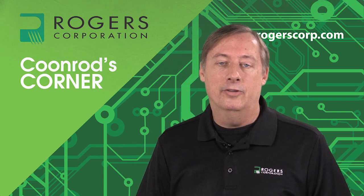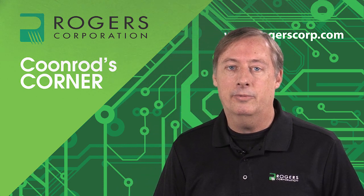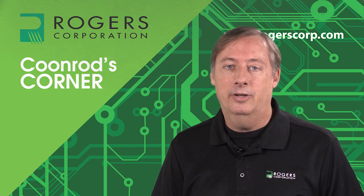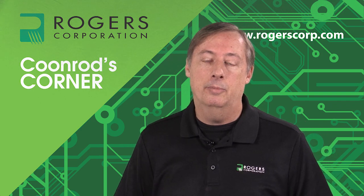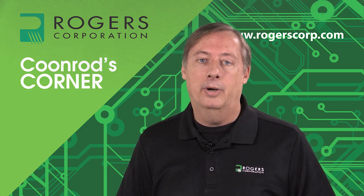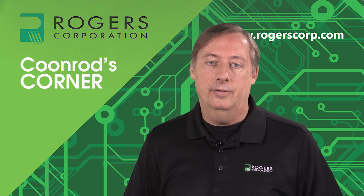We have found over time, as well as our customers, that the design decay values that we generate with a microstrip transmission line can be different than the decay values from other test vehicles. And that does make sense, actually, when you put a little bit of thought into it. So I'm going to explain some of the concerns here and why you can get different decay values on the same material when used in different test vehicles.